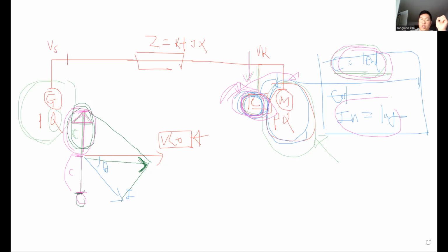The generator only needs this part, it needs to make Q here. Because this capacitor bank provides C near the motor, near the load, since we installed it, the power factor improved. Power factor is the phase difference between V and I, and why we use it is because of money, right? If we improve the power factor, it saves money. That's it.